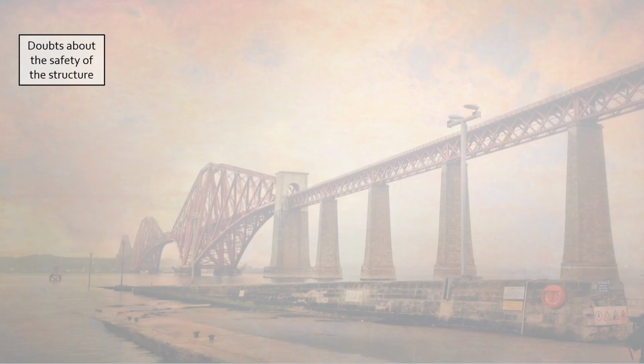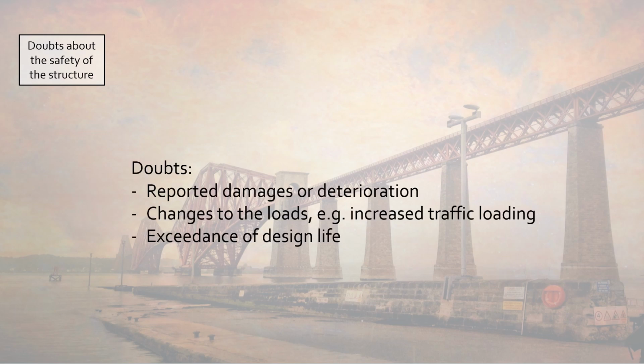So if we were the teams of engineers that should assess this bridge, if this bridge could be used further, what would we do? An assessment of an existing structure would typically start because you have some doubts about the integrity of the structure, or triggers as it is often called in standards. Such doubts can be anything from reported damages or deterioration, known changes to the loads it is exposed to, such as increased traffic loading, or just that the structure has exceeded its design life.